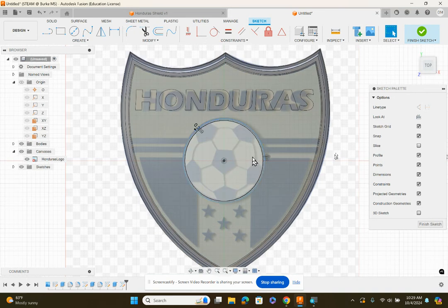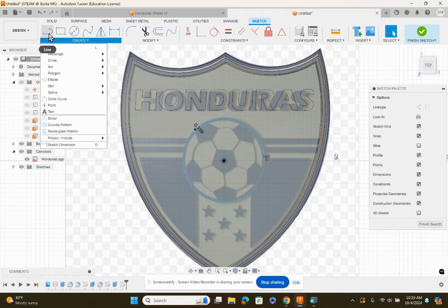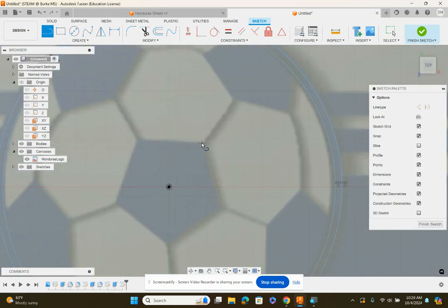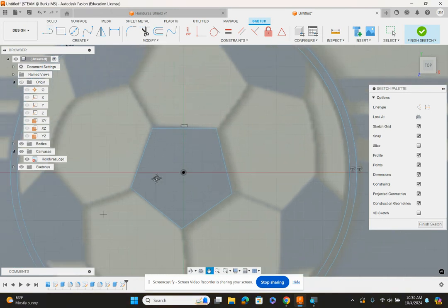Okay, so I'm going to sketch first, and then I'm going to apply features. So now I need a polygon, but I think it would be best if I use, because I can create polygons through here, but it would be best if I do the line tool to create these shapes, so I can go faster. So I could click here, make them straight, I guess. My image is a little bit off. And so I am going to have to cut the video here, because I don't want you to stick around watching me do this. Just remember to make sure that they're always closed.